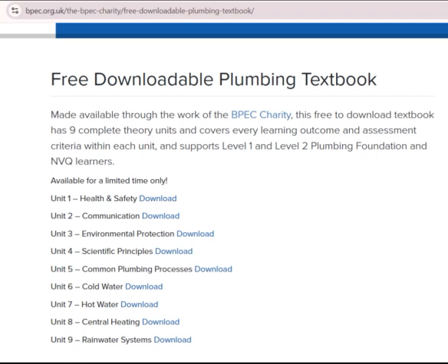Checking for leaks. AC 11.4 Identify the actions that must be taken when inspection and testing reveals defects in central heating systems. Inspection and testing of central heating systems can sometimes reveal problems that need rectification before the system is filled and brought into operation. Problems are always best remedied before the system is wetted, especially if it involves altering pipework and making leak-free joints.